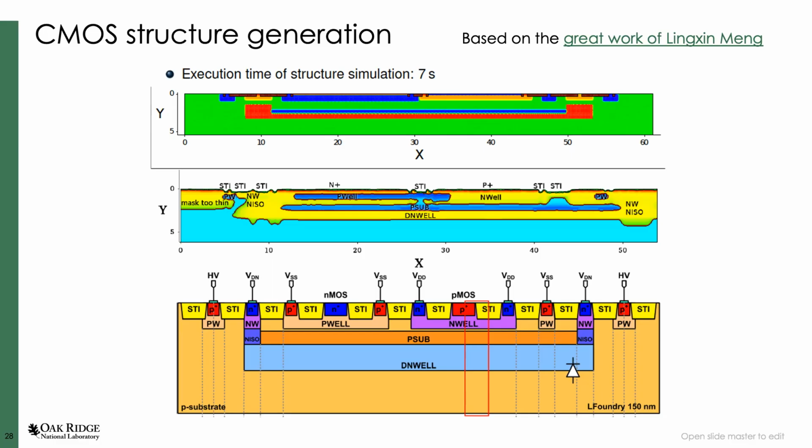Yeah, the meshing was the big problem there, because since they're doing very detailed simulation, the mesh in the first 200 nanometers of the surface where the oxide is was very, very detailed, because they were tracking that in detail. They're building the bird's beak and such, so they care about what happens to each NMOS and PMOS in there.